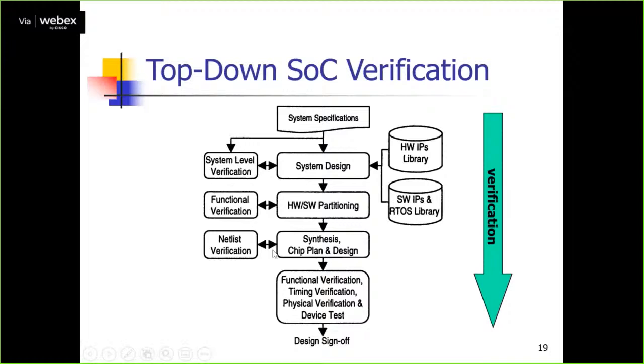So these plan, place, and routing go as PD, and then do the post synthesis functional verification, and do the timing analysis, different timing analysis, which is to be presentable. So it takes care of the functional parameters and then finally goes with a device test.